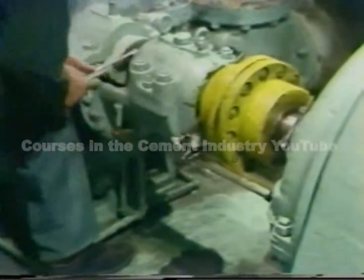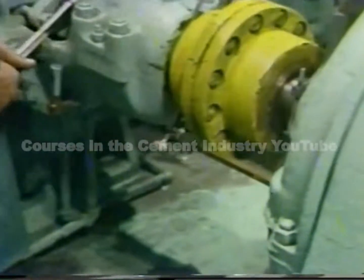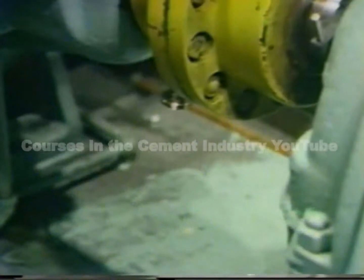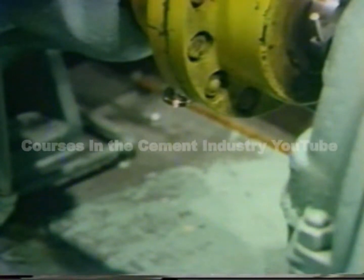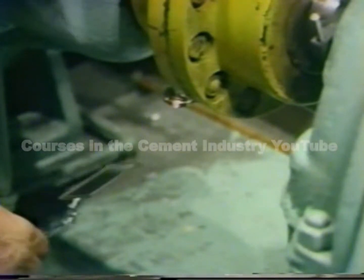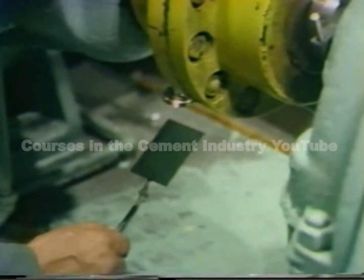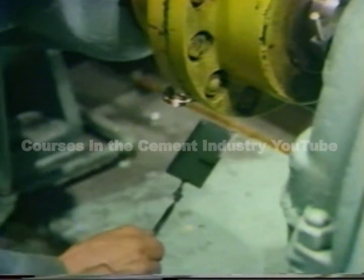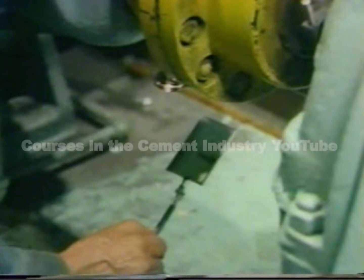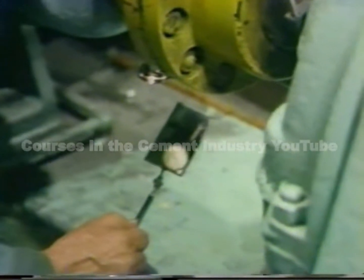The second position is read at the bottom. To read the dials in this position, an inspection mirror is handy. This may take a little practice since you're viewing a mirror image. He starts with the parallel dial reading and then checks the angular dial reading.